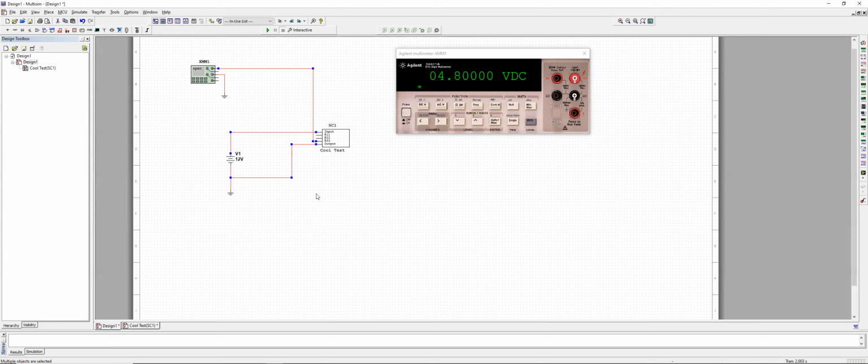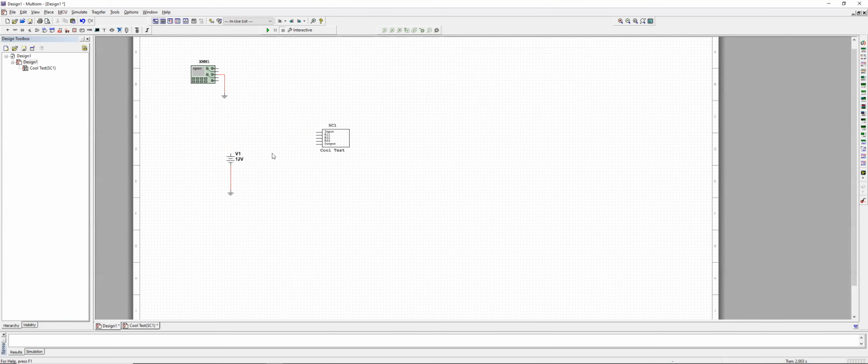But think about this. When you design circuits in Multisim, you have a lot of space on here. So you don't want to just cram all this stuff into your one space. You can actually create those subcircuits, and those subcircuits can be used to make modifications, for instance, to your frequencies. Like you might want to say, hey, I want to create a low pass filter. Instead of going through and looking for the components and double clicking on each of them, just go to your subcircuit and make the changes there.